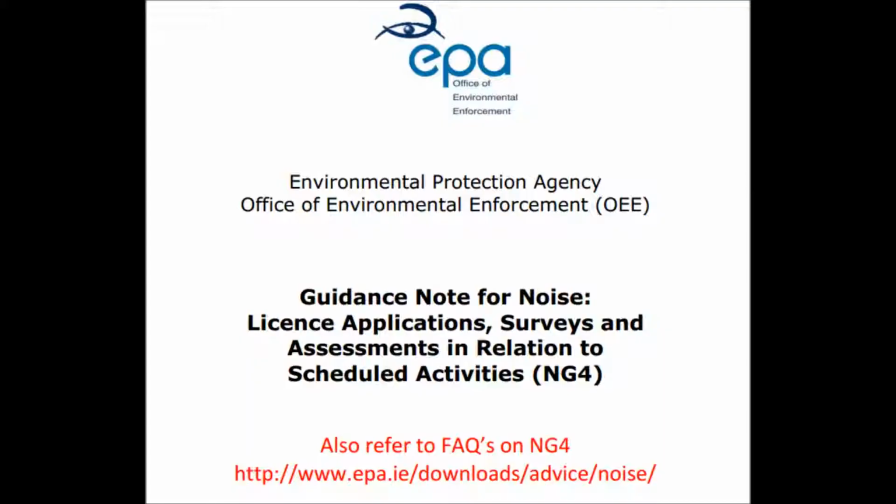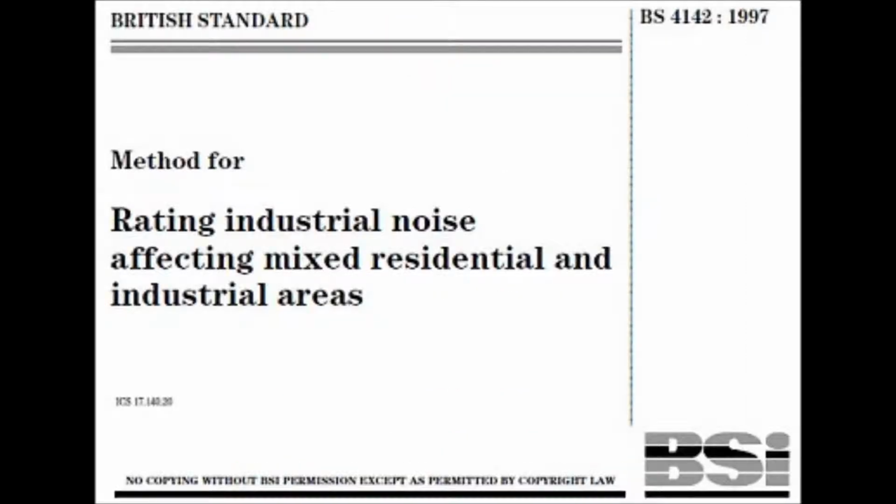The EPA document NG4 governs noise measurements for EPA licensed sites. Many local authorities would also reference this document. For assessing whether noise is likely to generate complaints, BS 4142 is the de facto standard. Many Irish local authorities would reference this document.